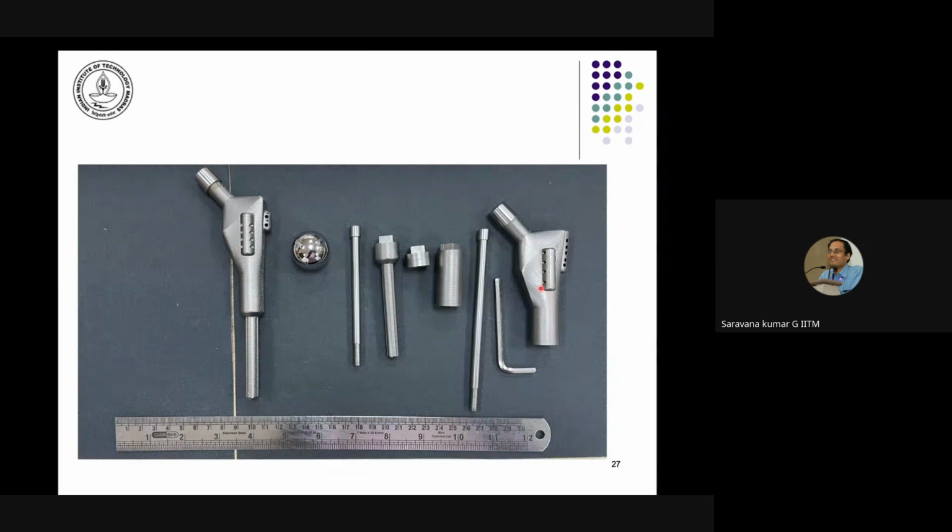We are also trying to work on the qualification side, particularly in aerospace, where Semilac is there. So change is happening, and also the laser technology that people are able to access. With multiple lasers, the time to manufacture can be reduced. Today people talk about 4 lasers, 10 lasers. That means it's not one laser fusing the metal but, let's say, 4 lasers, like parallel processing, so you can make the component faster. I'm told at least China is building farms of additive manufacturing, an entire plant having tens of additive manufacturing machines making components.